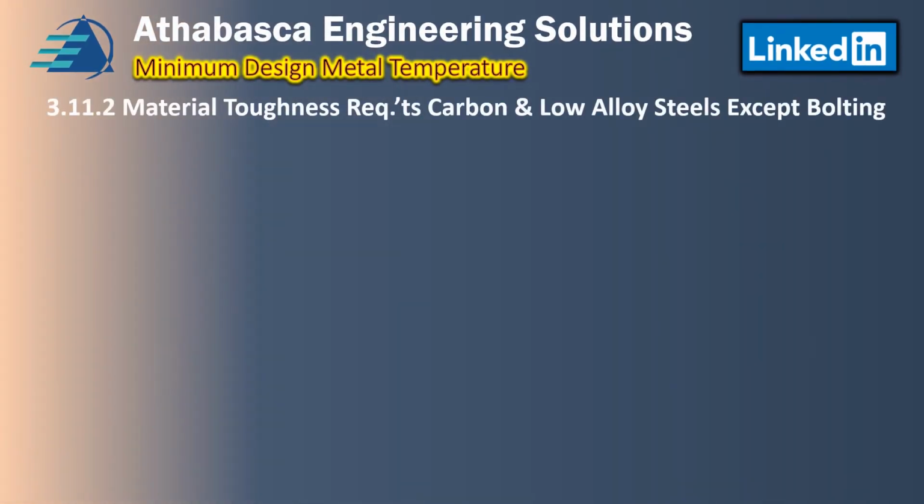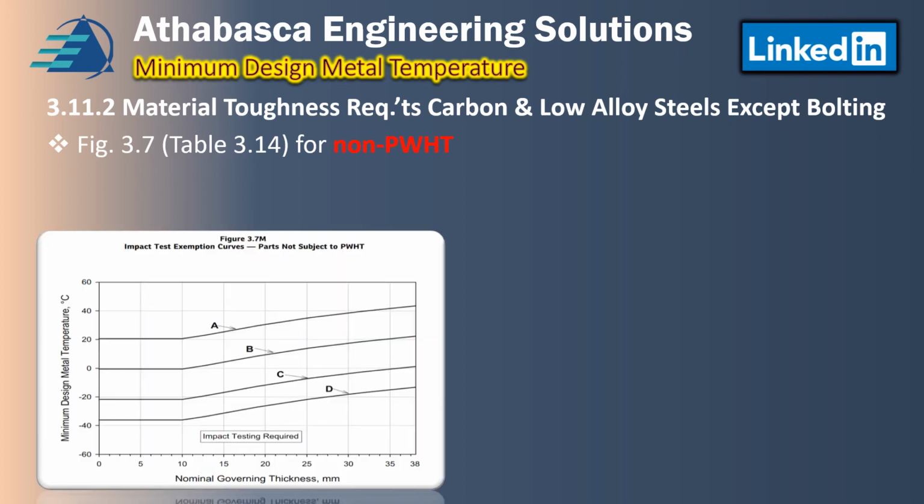Look at 3.11.2, material toughness requirements for carbon and low alloy steels, except for bolting where we use tables. In 3.11, you can also use table 3.14 if you want an exact answer. For presentation purposes, I tend to like to use a chart because it's easier for people to understand what you're trying to do. But if you're using a computer model and you want more precision, then the table is the way to go. So here is the one corresponding to parts not subject to post-weld heat treatment.